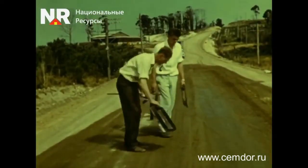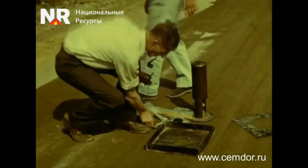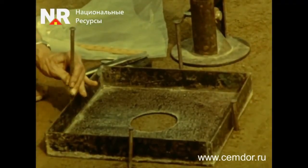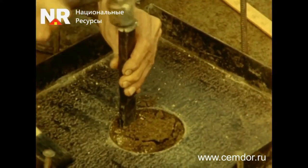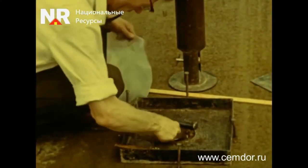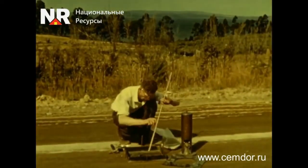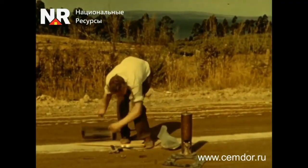The density of the compacted structural layer is determined by directly extracting a sample and sending it for analysis. The thickness of the structural layer is measured, and the volume of the extracted material is determined by filling the hole with sand of known density.